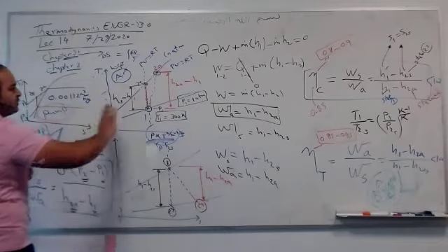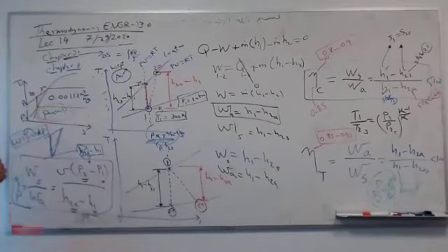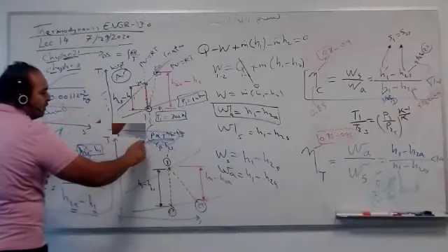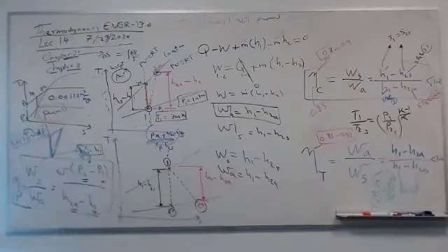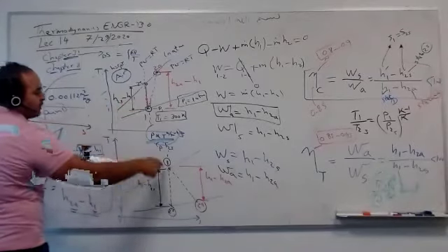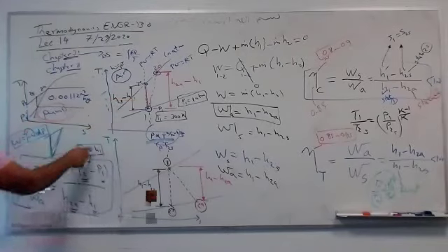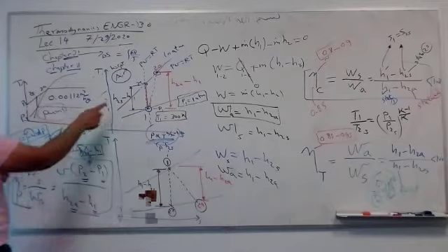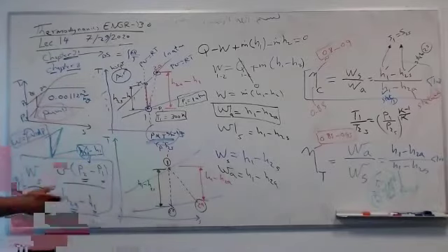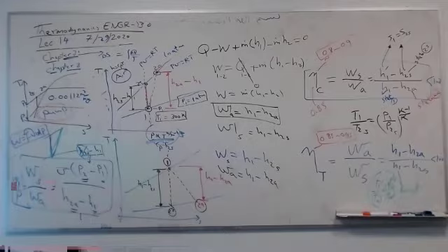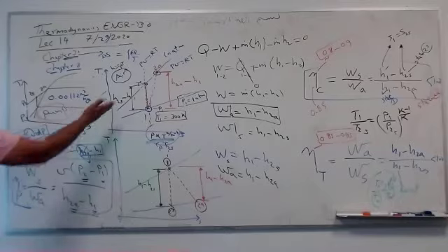So we have 2S isentropically. Delta S between these two points is 0, or you can use the isentropic correlation. So 1 and 2S are isentropic. It's the minimum work to pay, or the maximum work you can get, from a compressor or even a pump, or from a steam turbine or even an air turbine. We still use it sometimes for liquids, or steam going to liquid, as we will see in the Rankine cycle, and also for the Brayton cycle for air.